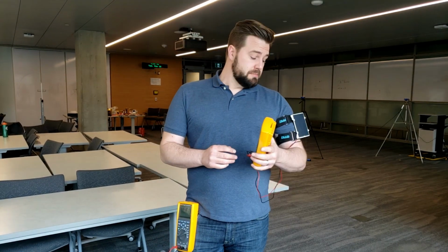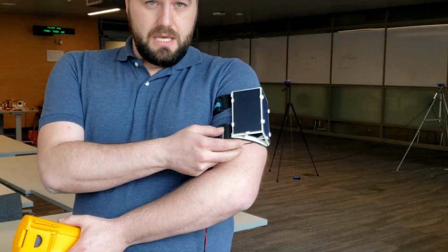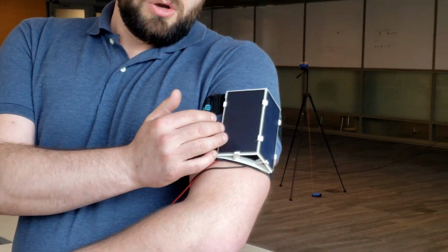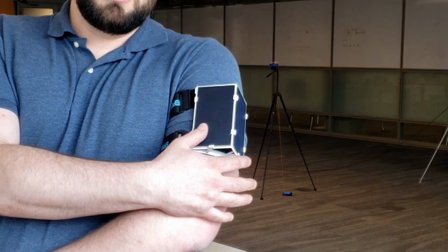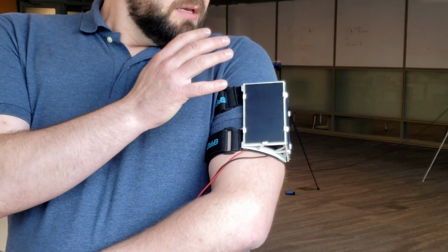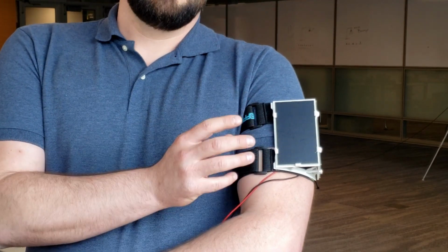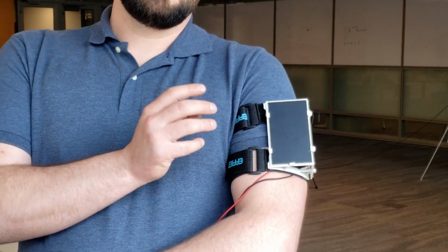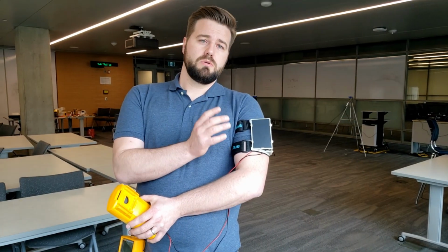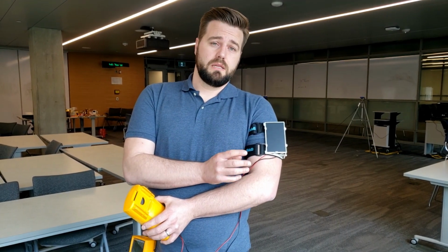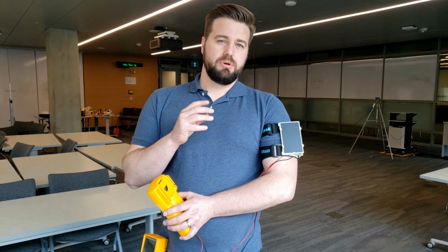Now, the first and simplest of these two harvesters is the solar harvester here. What I have is just on an armband, a really interesting 3D printed housing, and it is showing two 1.2 watt solar panels that are high efficiency, about 22% efficient. It is coupled with, which can't be seen, a lithium battery in here, and then it uses what is called an MPPT charger, which is just a special maximum power point tracking solar charger. It's used because solar panels have pretty terrible load regulation, and this uses an algorithm to help maintain the voltage where the solar panels output the most power.